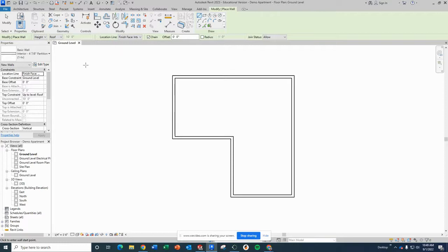And it's trying to bring these all the way up to the roof. I'm going to change them to be unconnected so I can set the interior walls at 8 feet tall. Because the interior walls would basically come up and touch the ceiling. They would kind of end where the ceiling level is, which in most homes would be at an 8-foot height. So I'm going to put 8 foot, hit enter, and there we go.